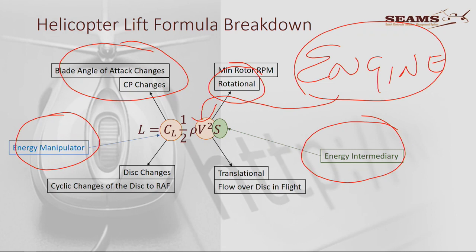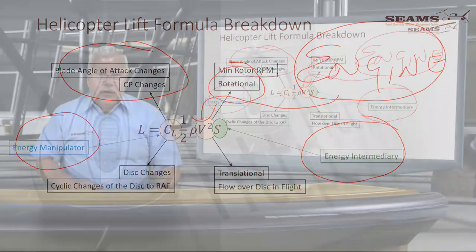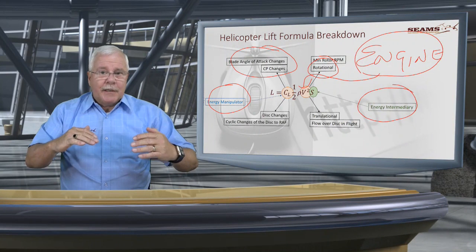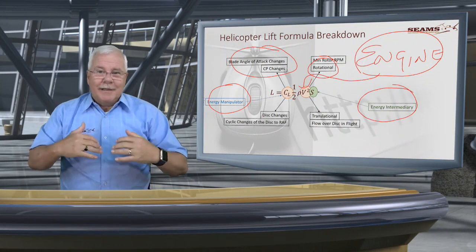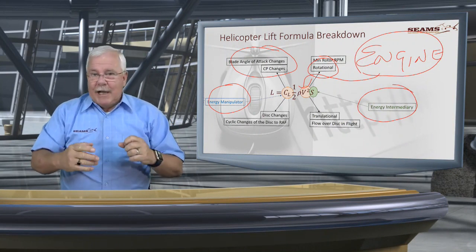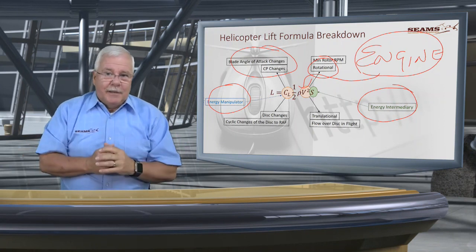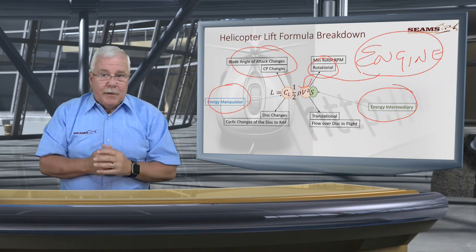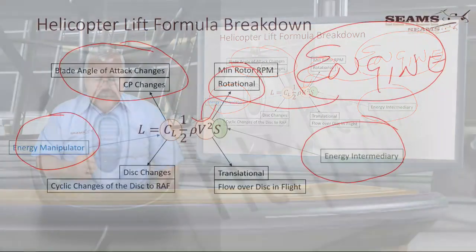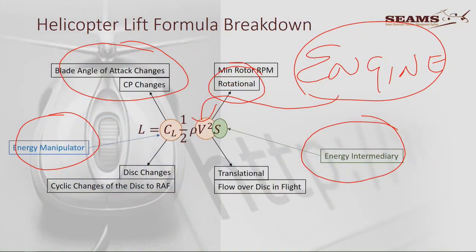What is it doing? If you increase the pitch, you are actually increasing the torque demand. The engine puts in more fuel and it stays there, and now it starts creating the lifting force as required. Great. At the bottom here, translational, we said if you get into the hover and there's more power available, now you can start going forwards.